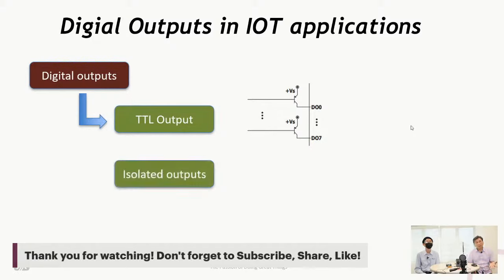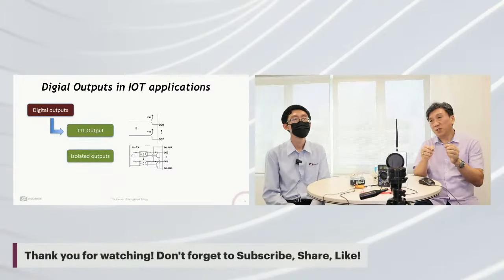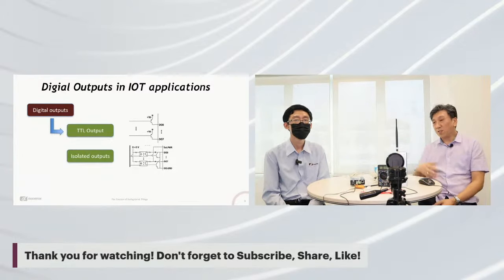From there we have the isolated output type. Here the optocoupler is pointing out instead of in. Whatever triggers in your system, the IoT gateway or controller, activates the opto transistor on the isolation barrier, and that triggers the output. This is the more preferred way in industrial applications, where you want to isolate both your digital input and digital output from the external world.